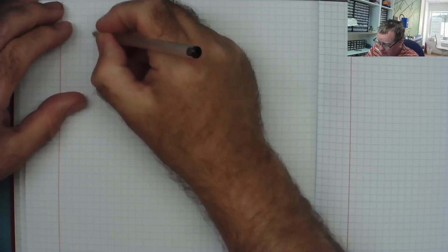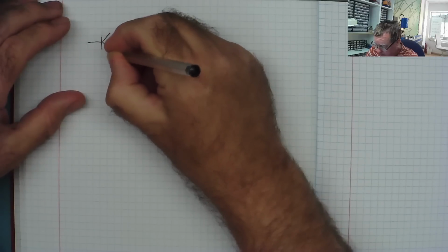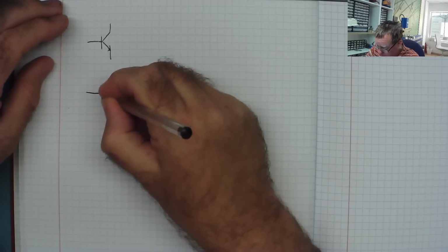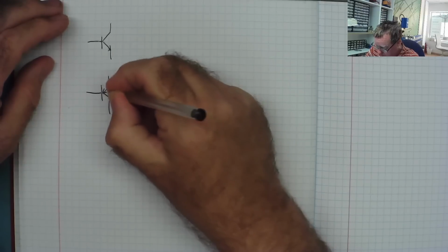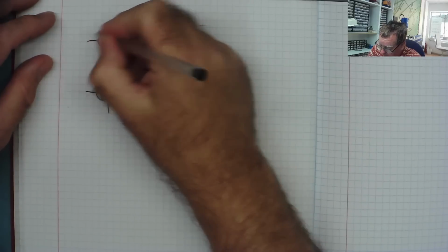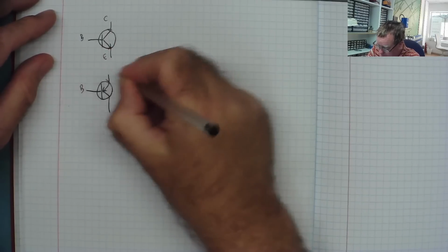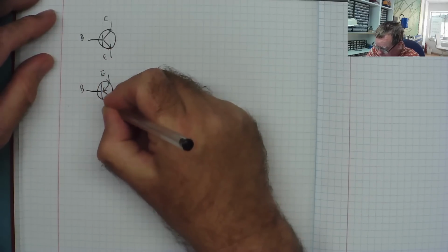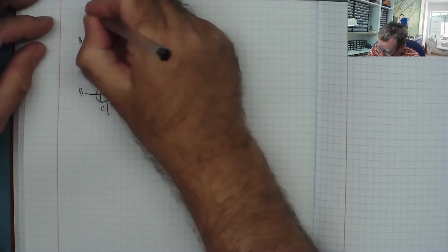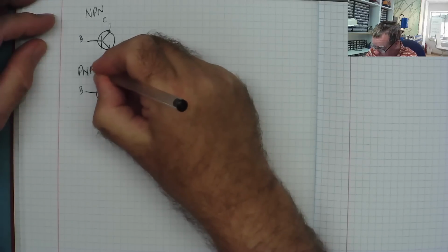So you may well know, for a bipolar transistor, we have NPN, like so, and we have PNP, which you can draw this way up. The difference being the way the arrow points, and the pins are the base, collector, emitter. And I drew this one the other way, so base, emitter, collector, and it'll come clear why I drew it the other way in a minute. The equivalent of an NPN transistor is an N-channel or N-type MOSFET.